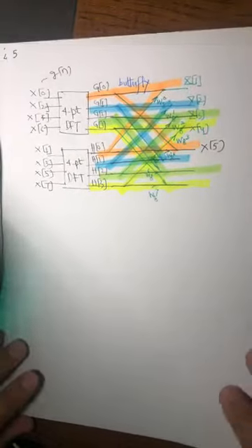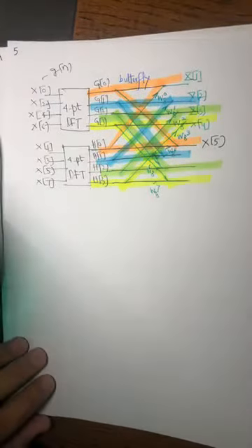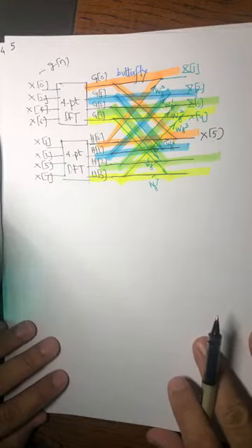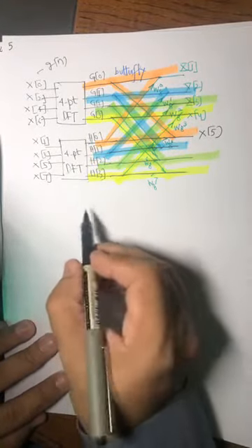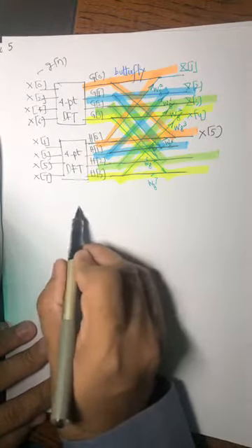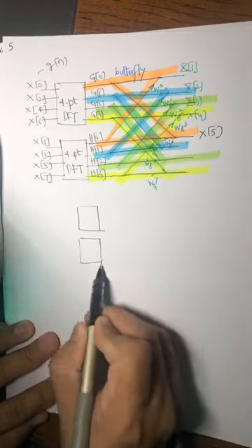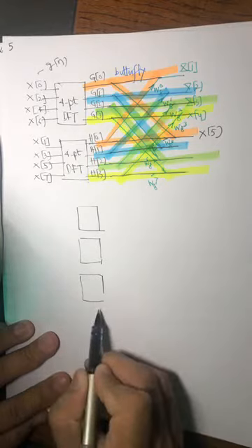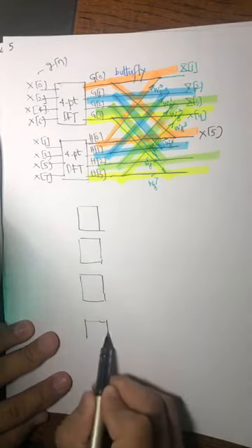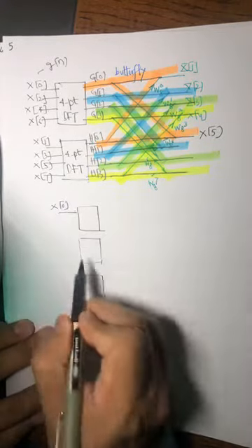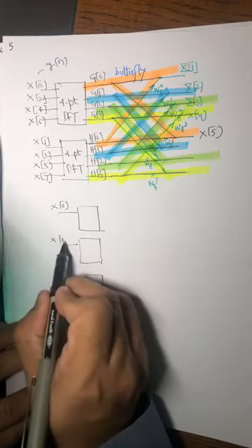But I just mentioned that even these 4 points can be split into 2-point DFTs. So there is no point in taking even the 4-point DFT. So, interesting, like you have x0. Once you split, you have 4 of these. You give x0 to this one and x2 to this one.